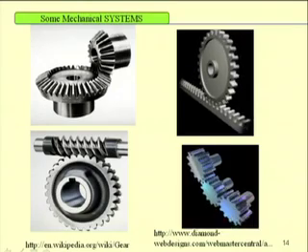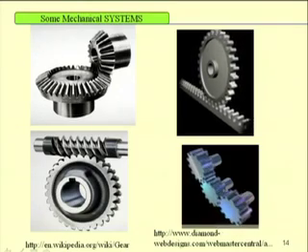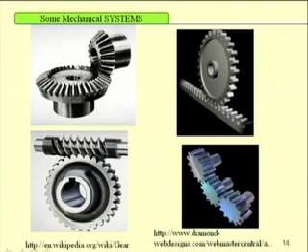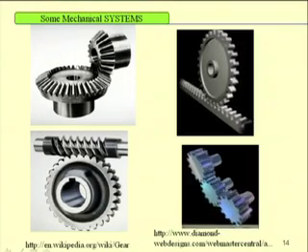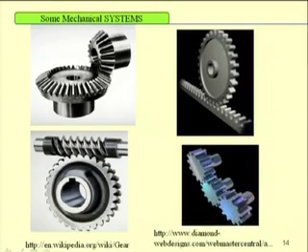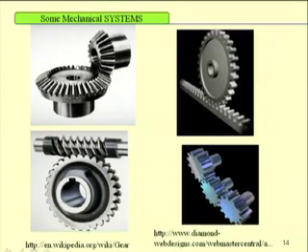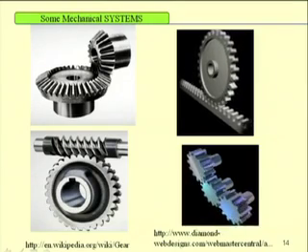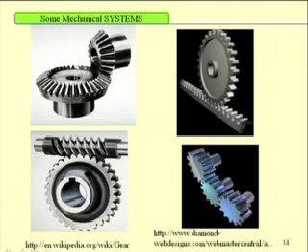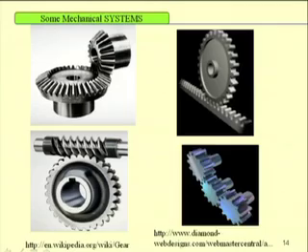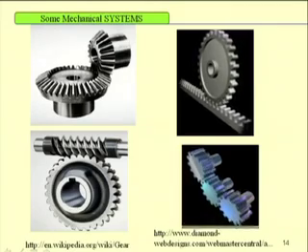For example, in the case of rack and pinion, you can convert this system to an equivalent rotary system or an equivalent translatory system. If perfect rolling is assumed and there is no manufacturing defect, you may neglect the vibration in the system. But due to the presence of manufacturing defect, backlash, clearance, most of the time you may see vibration occurring in these types of systems.